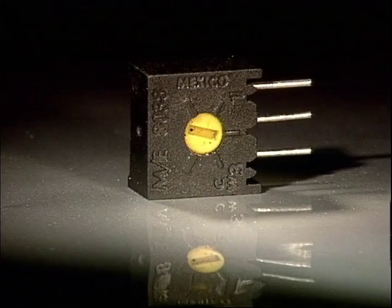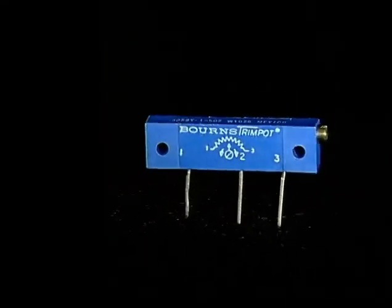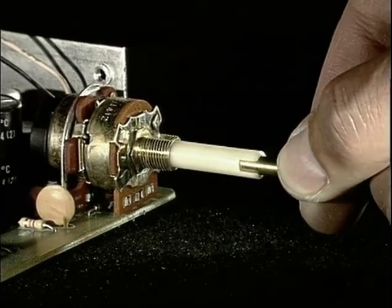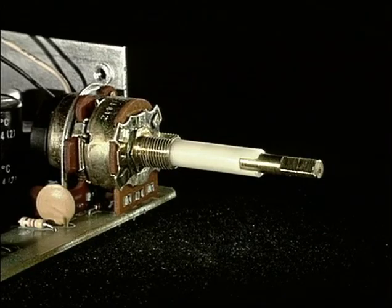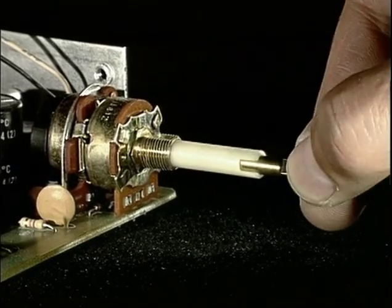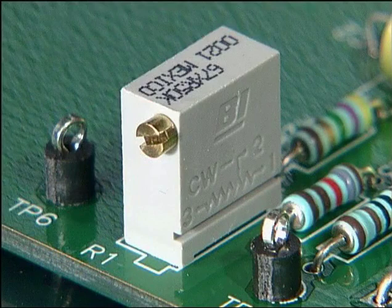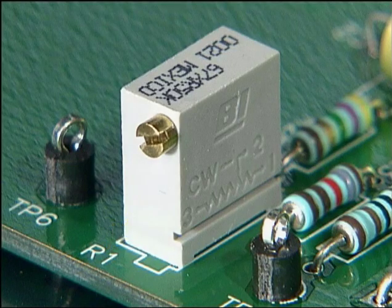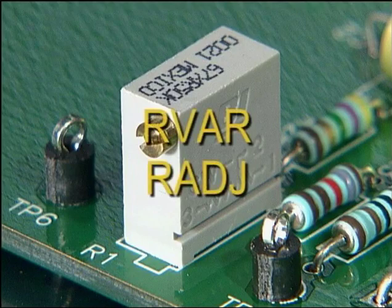Another type of resistor is called a variable resistor or potentiometer. These components may also be called trimmers or trim pots. Variable means that the value or resistance of these types of components can be changed or adjusted either by turning a shaft or sliding a contact. The maximum value is usually molded into the component body. Along with the letter R, the reference designator for variable resistors may be VAR or ADJ. Variable resistors typically have a non-symmetrical lead pattern that only allows them to be installed one way.